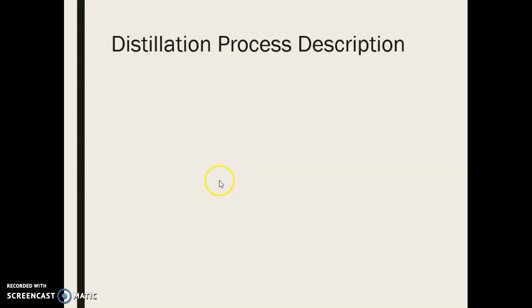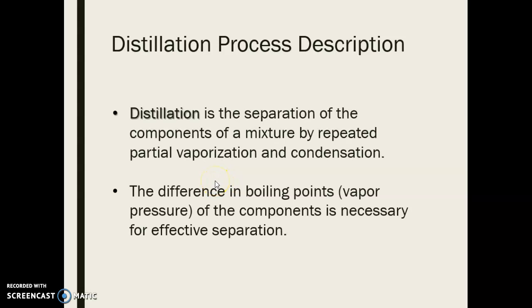Okay. Distillation is the separation of components of a mixture by repeated partial vaporization and condensation. So again, distillation occurs at each stage of the column. And there are so many stages, and you get better and better purification as you go up the column. The difference in the boiling points, the vapor pressure of the components, is necessary for effective separation.